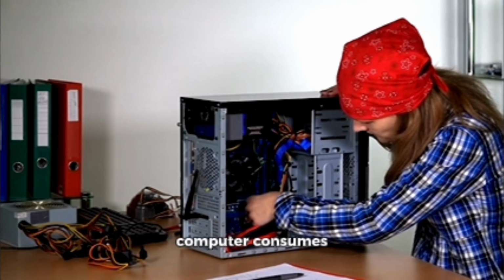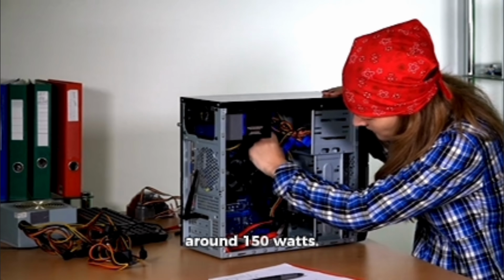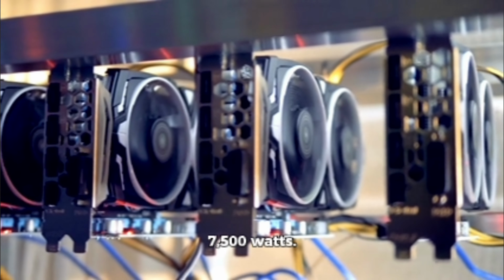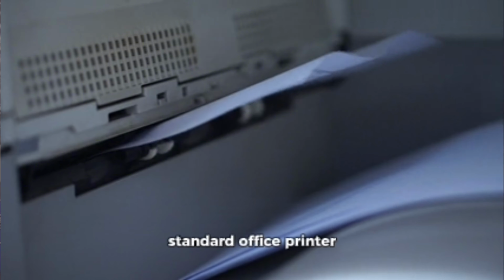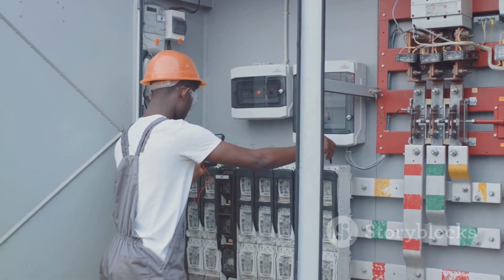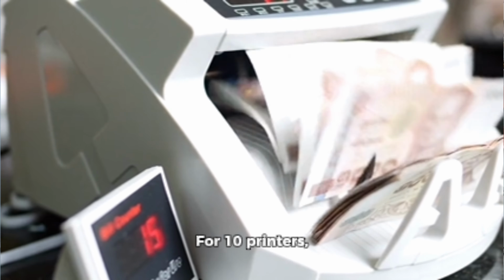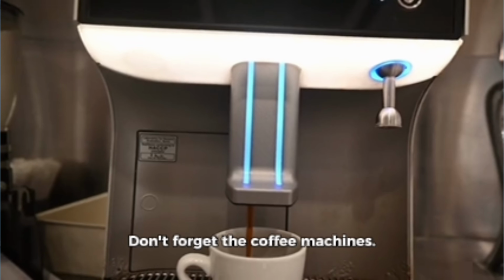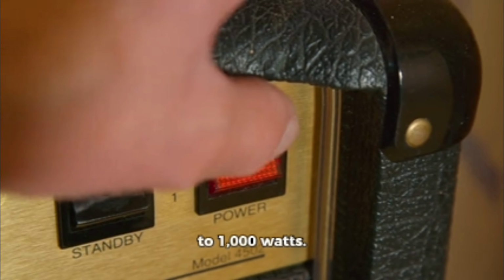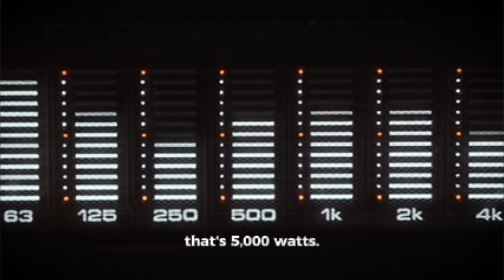A typical office computer consumes around 150 watts. If you have 50 computers, that's 7,500 watts. Printers vary, but a standard office printer uses about 500 watts. For 10 printers, that's 5,000 watts. Don't forget the coffee machines. Each one can use up to 1,000 watts. If you have 5, that's 5,000 watts.